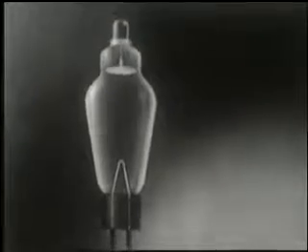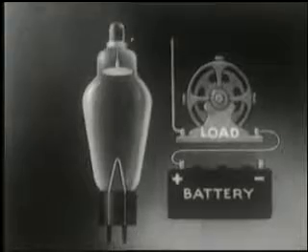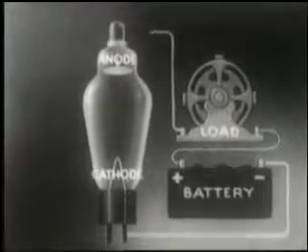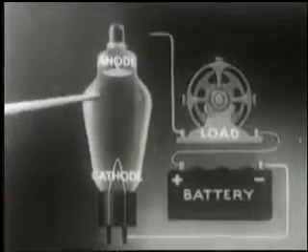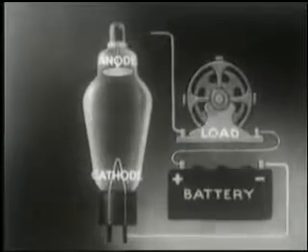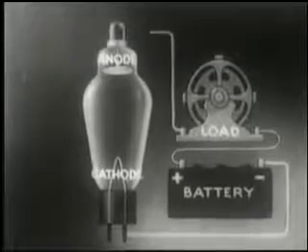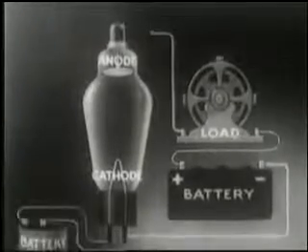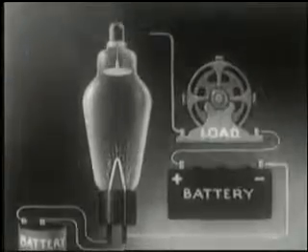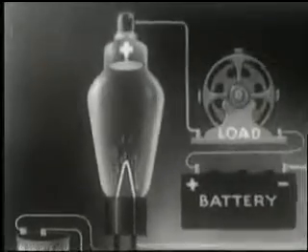Switch that can connect, for instance, this battery and its motor load. One power lead comes to the anode, the other lead goes to the cathode. When this switch is open, the contacts are insulated from each other by a vacuum, or by some inert gas inserted into an evacuated tube under low pressure. To close this switch electronically, all we need do is heat the cathode and give the anode a positive potential. Then here's what happens.